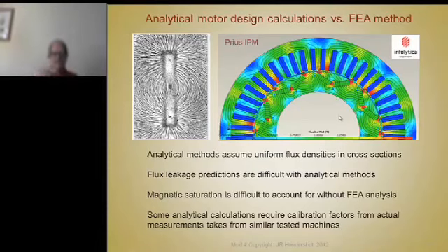But by using finite element analysis, we find out that that's not the case at all. Parts of the circuit saturate, like these little sections saturate, these little sections saturate. Not all the flux from the magnet goes through the stator. So my hand calculation has a big error in it in terms of the flux density in the yoke, and it's certainly got a big error in the average flux density in all these teeth. You can see because I've lost some of the flux. I even lose from saturating this. That reduces the saturation here, reduces the flux out there. So the finite element solutions give you a much more accurate representation of the flux distribution.